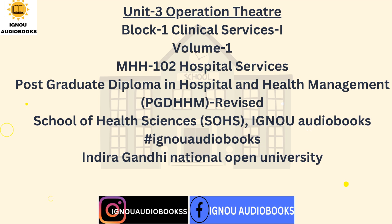3.5.8 Lighting. Lighting, or in other words illumination in an operation theatre, is an important requirement for the efficiency of the services. It is essential to provide adequate light for the surgeon, anesthetist, nursing and other staff in the operation theatre complex. The quantity, the quality and the direction of lighting are some of the factors to be considered. The principles of the lighting requirements of an operating room are: lighting of high intensity, capable of speedy and accurate adjustment with good focus, producing minimum heat, illumination of depth of the wound without glare on the surface, near daylight in color, shadowless, freely adjustable to any position or direction, spark-proof and safe where inflammable gases are used.